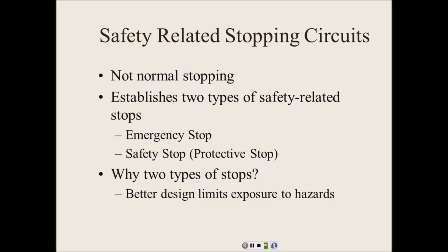Safety-related stopping circuits, these are not normal stopping. Every one of these robots has a button on the teach pendant that you can use to perform a normal stop. Some of them call it hold, some of them call it pause, some of them call it stop. That's the button you're supposed to use to stop the robot.